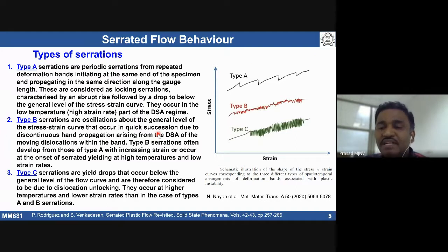In the previous lecture and today, what we are talking about are plastic deformation instability conditions, the phenomena like yield point phenomenon, strain aging, dynamic strain aging. These are plastic instability things, so one should avoid them. If there are these kinds of bands, we are going to see formation of a rough surface, and the rough surface creates a problem in the finished components after forming.